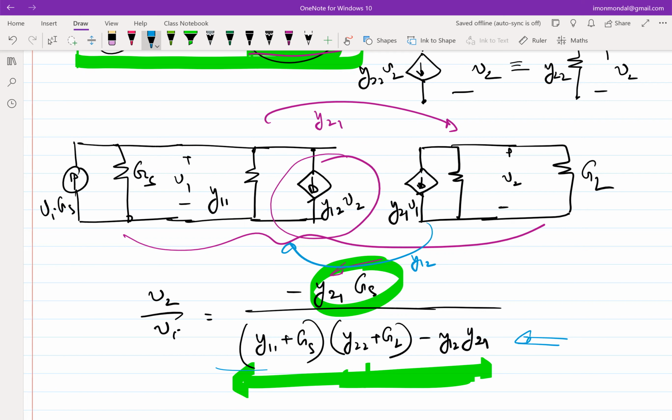Whatever the speaker is sending back, effectively that. Yes, that is a Y parameter. But what is this physical thing? The physical thing is a function of how you have set up the system. In this case, a Y parameter is a function of the quiescent conditions. Note that this feedback system is not necessarily limited to electrical systems. It can be a hybrid system. Here it's acoustic going into electrical, going back to acoustic. The loop is through multiple systems.